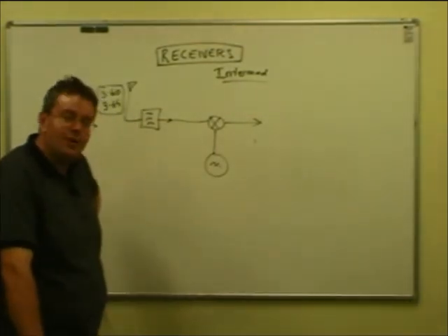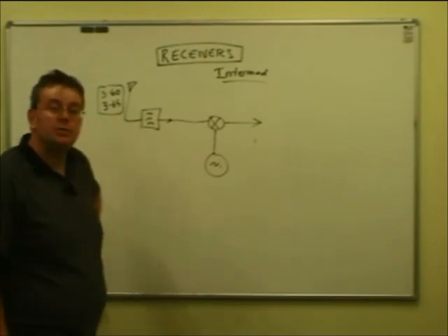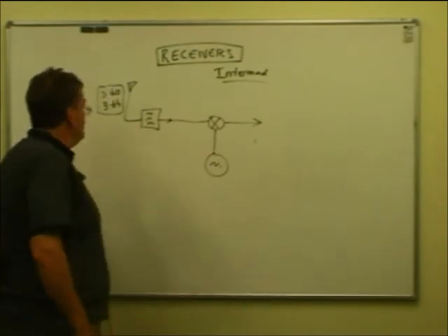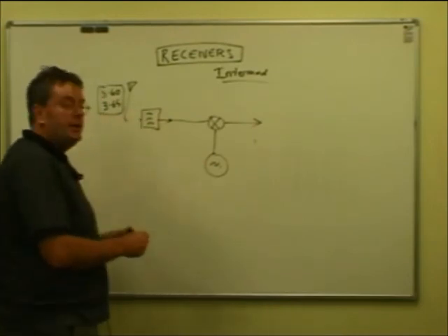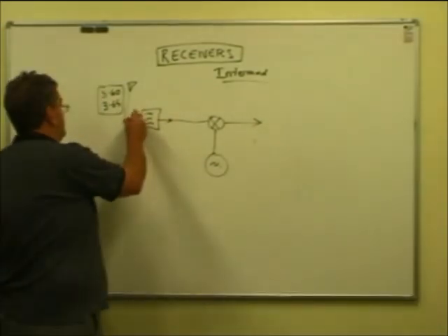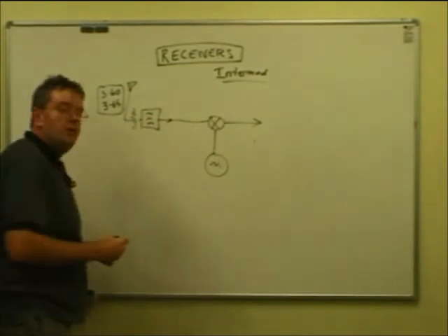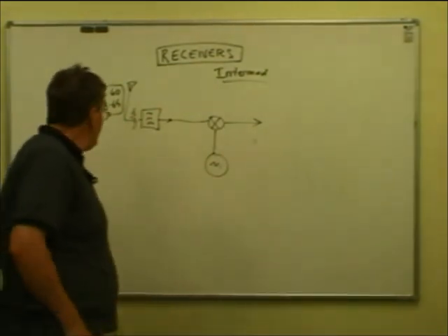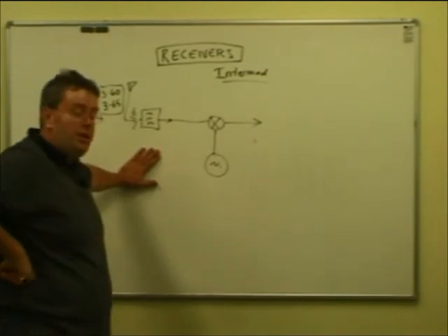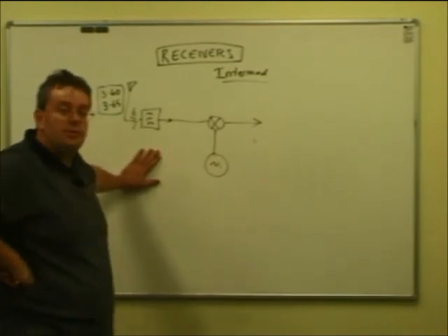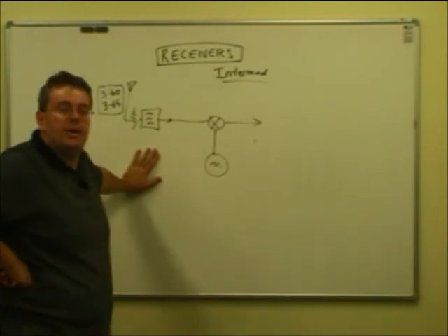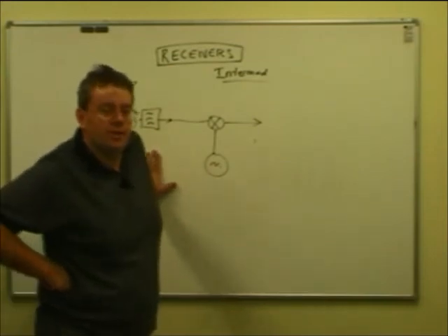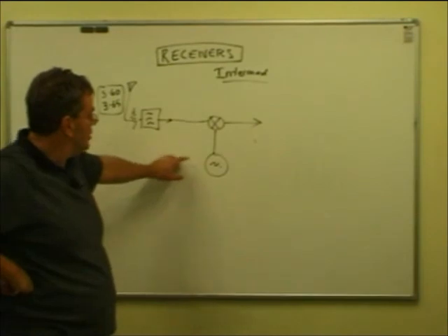And that's why you find on radios that they seemingly do the ridiculous sometimes: you can actually switch in, between the aerial and here, an attenuator. The symbol for it is kind of a resistor thing. You can actually switch in a resistor arrangement to cut back the signal strength. Yes, it will add noise to this. It will degrade the signal-to-noise ratio of your receiver. But if most of the signals around are very strong, and all you want to do is hear strong signals during the contest for most of the time,